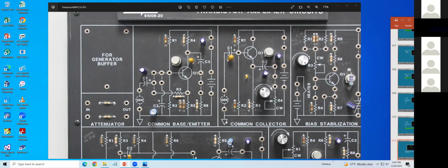And today, I just bring up one thing. When they say they want to apply a sine wave, you have to get the sine wave from the generator, 300 millivolt peak to peak. How can you get that small voltage? That's that offset thing you talked about, like pulling out the knob.